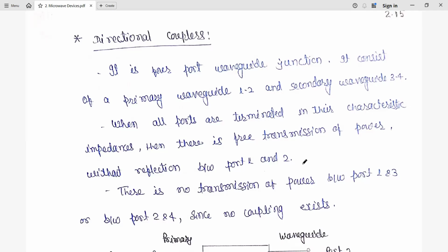Directional couplers: how the name comes about, and how they provide directivity. Here we'll look at two-hole directional couplers, which have four ports, and we are going to see their S matrix, and also the expressions for the coupling coefficient as well as directivity.